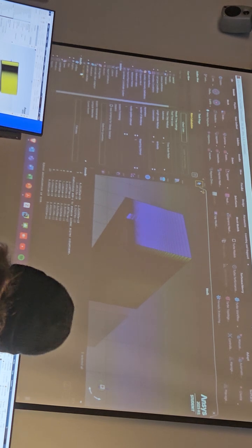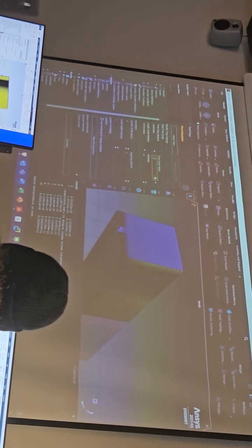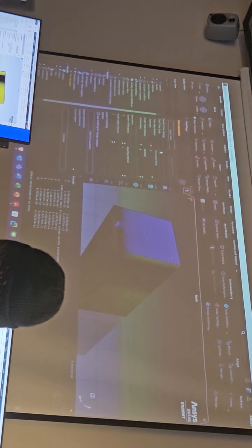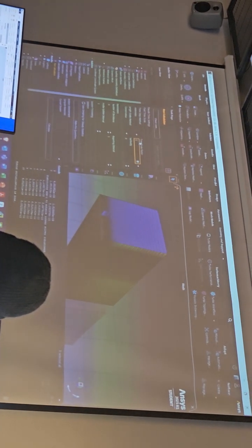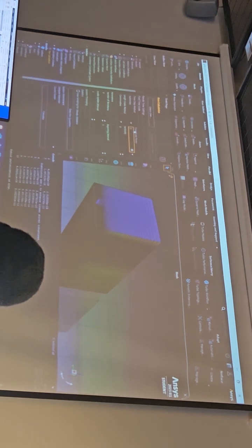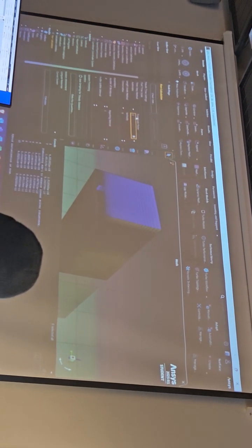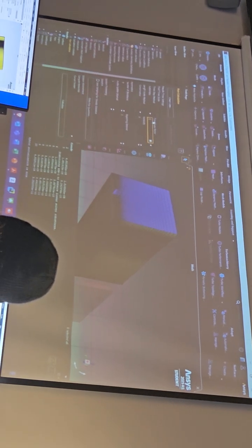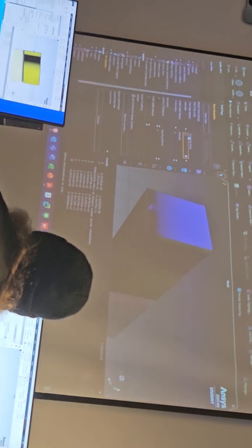And then we can go and run calculation, where we can set the time scale factor. Also this value here, you can adjust it if you see that you have numerical difficulties to converge. That means that you are reducing the time step. So the solver is applying a lower time step to get to the steady state solution, because we are still solving for a steady state problem.